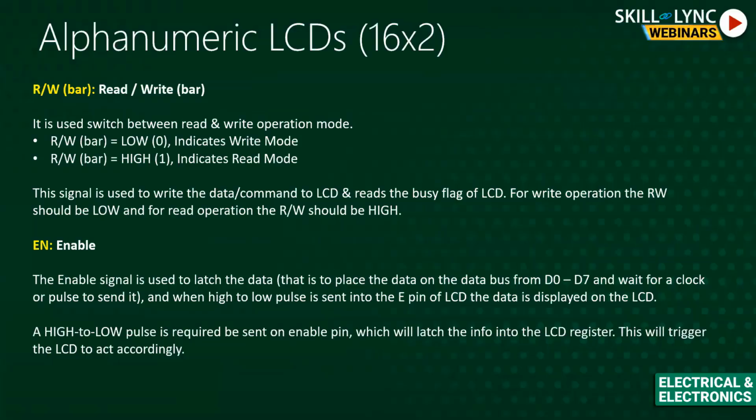The next important pin in the LCD is read/write bar. Read/write bar specifies that if the value is 0, it indicates the write mode, because it is write bar, and the value 1 says that it is read mode. So depending on that, I will say whether it is read or write mode.